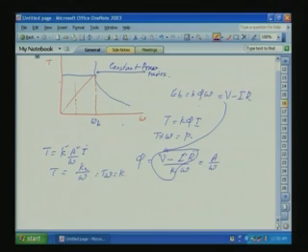So we are using the two degrees of freedom, one is the armature control, one is the flux control. When we do the flux control, we said it is a constant power region. Here this region is called the constant torque region. Constant torque region means we can have constant torque irrespective of the speed up to the maximum. But above base speed, torque is not constant, the maximum torque available is limited. So it will go like this.